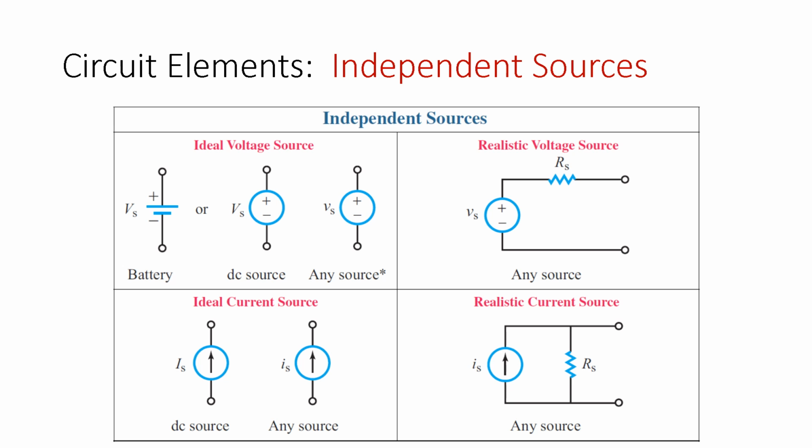But the battery is also getting hot because it has an internal resistance. As that current flows through that loop, the battery itself is getting warmer and taking some of that energy out as well. There are a couple of really cool mechanisms for that we can look at in the future, but just know for now that any ideal voltage source has a resistance essentially inside of it, in series with it, mathematically.